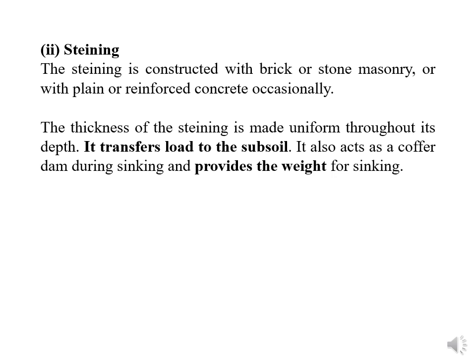It also works as a coffer dam. Coffer dam means it is going to restrict the flow of water. The water will not go inside the well because it is going to stop the water, so that we can remove the water through pumping and make the river bed dry for the construction purpose, or for dredging, or for removing the soil from the edge of the well, right?